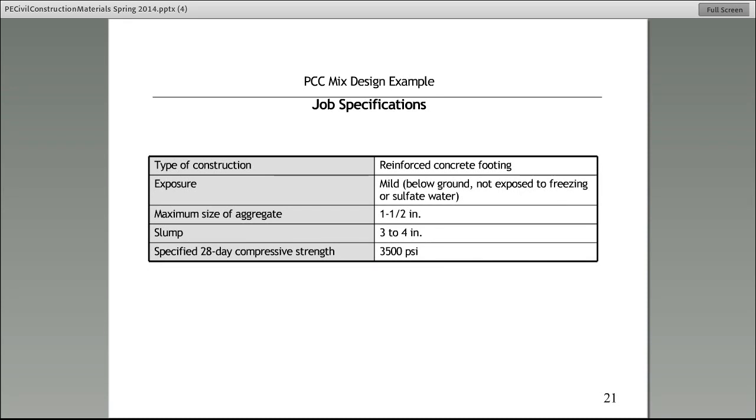Ryan is asking, is the standard deviation an f'c value? It's not an f'c value, but it carries the same f'c units. I think that's what you're really asking. So yes, the standard deviation is in terms of psi.